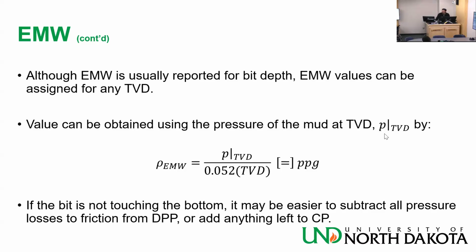That's why, as we're going to see later, it's a common practice before they start drilling a section to run the pumps and measure the pressure on the surface. And that pressure on the surface is an indication of the frictional losses at those conditions. Now, when you are drilling, obviously you make your hole deeper and you have more friction, but you already have a good indication from the beginning of that section. Then if you change something, say the mud weight, you need to do that again.